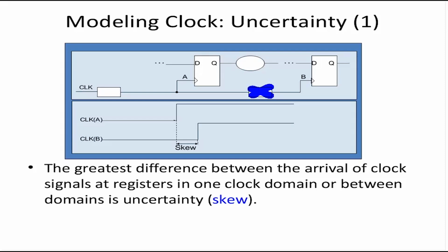So for clock tree estimation, for example in a particular technology, the designer might say, okay, I'll keep a blanket uncertainty of 200 PS. So you apply that uncertainty for all the clocks in the design, 200 PS standard for all the clocks. There can be different guidelines depending on how big your block is, what technology your chip is in, and so on.